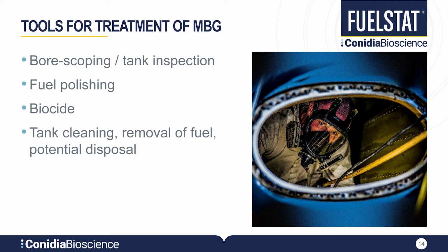Second, regular use of the same biocide can create an environment where the organisms may become immune to the treatment as they evolve to the environment, in a similar way to the differing strains of COVID have been doing. So changing it up every now and then or reducing its usage frequency is not a bad thing.